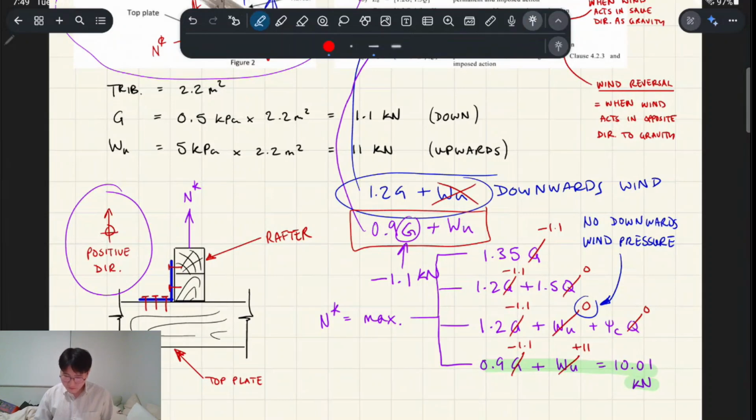And you'll see later when we're talking about the European load combinations as well, that you always have a reduction factor when you're considering dead load as beneficial, right? So the 0.9 is beneficial dead load, whereas the 1.2 is an exaggerated dead load for when it's detrimental, right?